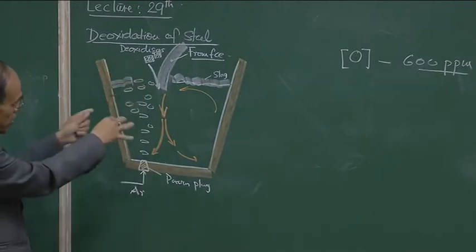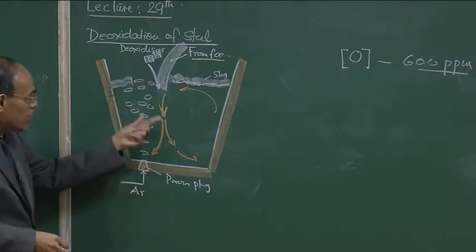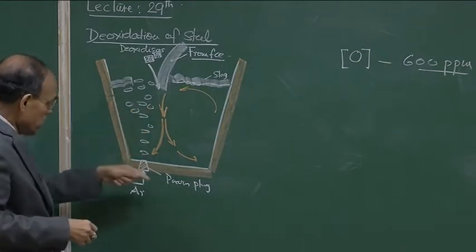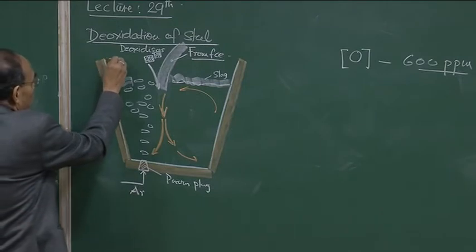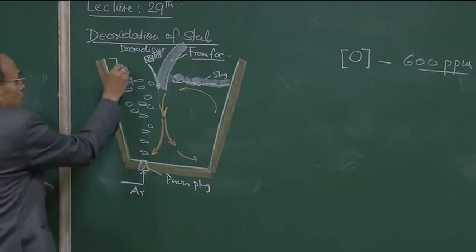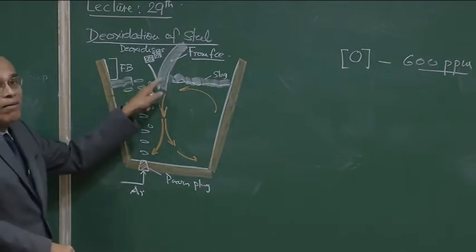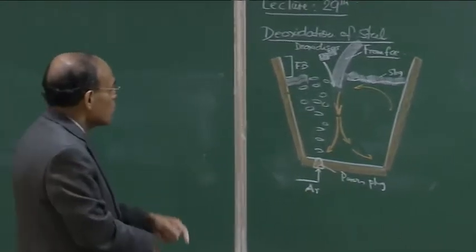So, this depicts a scenario where molten metal is being tapped from a furnace. The ladle is almost nearly filled. We have a freeboard height available here, and gas stirring is also going on simultaneously, because the moment this stream is exhausted, we require some amount of stirring in the system.